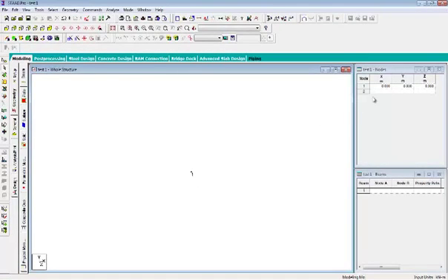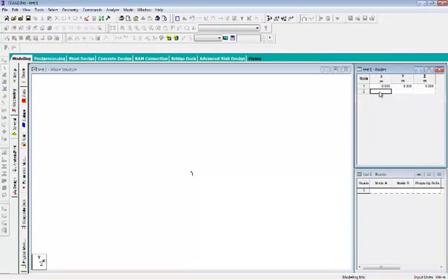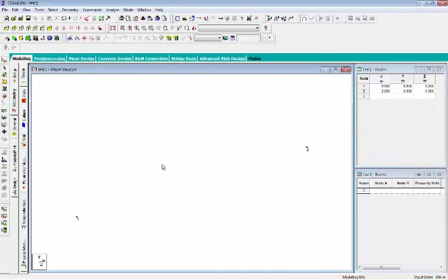Now if we add another node, say at 2 0 0. Just you see the two nodes are there. To scroll down or scroll up, you just need to roll the mouse wheel. So now we have created our first nodes 1 and 2.